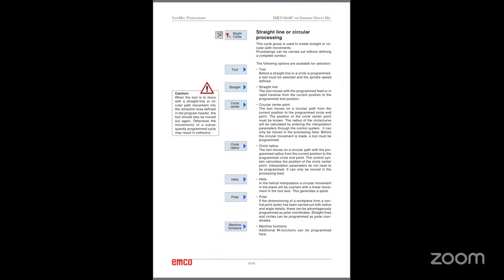Then helix means the circular movement, linear z movement. A combination of circular movement plus linear z movement. This motion is what is called helix. This will create a circular movement plus linear z movement, so this will form a spiral path. So go to helix. Here the pitch of the helix is say 1.5, z is 25, I is 25, J is equal to 25. Helix.